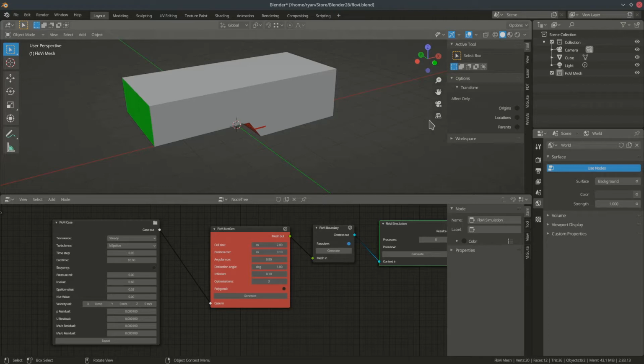So one of the first things you have to do if you're going to do a FloVi analysis is that we're going to need an OpenFOAM installation on your Linux computer, and I'm using OpenFOAM 8 from the openly, freely available community edition of OpenFOAM, and we need to tell the vSuite where that installation is.